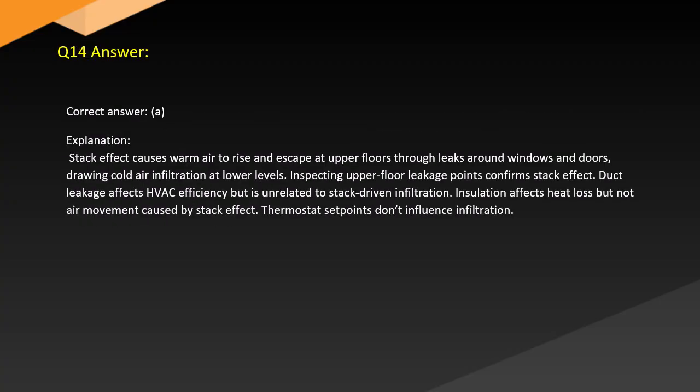Answer. Correct answer. A. Explanation. Stack effect causes warm air to rise and escape at upper floors through leaks around windows and doors, drawing cold air infiltration at lower levels. Inspecting upper floor leakage points confirms stack effect. Duct leakage affects HVAC efficiency but is unrelated to stack-driven infiltration. Insulation affects heat loss but not air movement caused by stack effect. Thermostat set points don't influence infiltration.